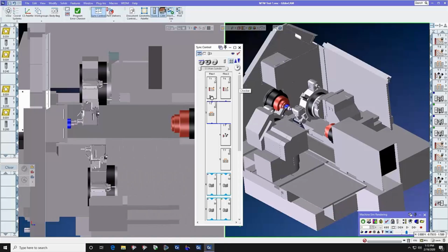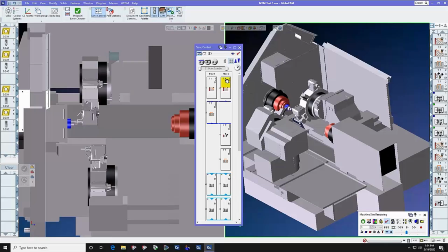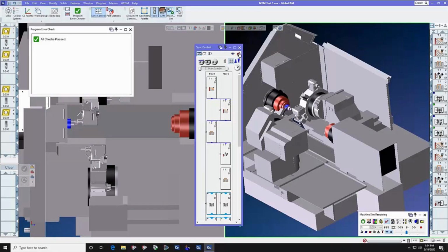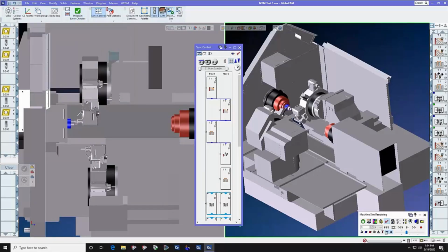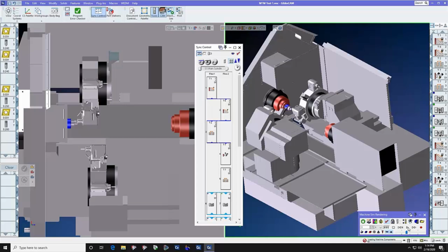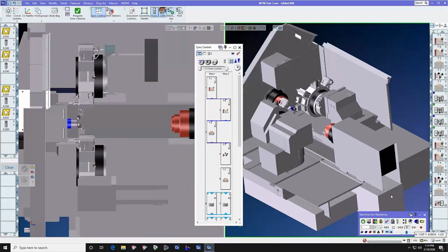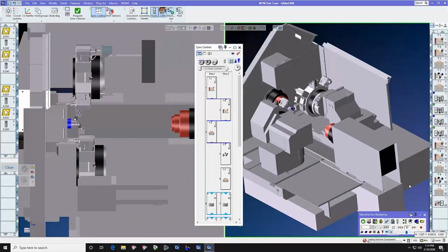We're going to put the synchronization back in and tell op2, the top of op2, to wait until the end of op1 to do its job. And we use the program checker to tell us that all checks have passed. We'll do a quick run back to the beginning of the program, and we'll see that now everything is okay.